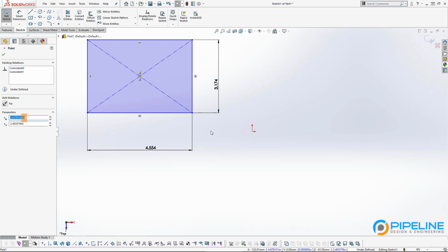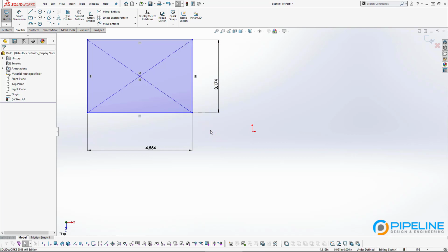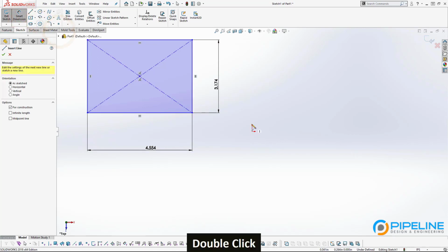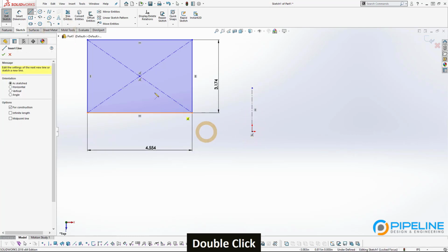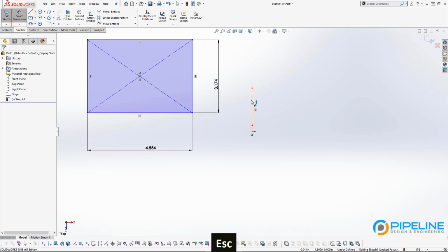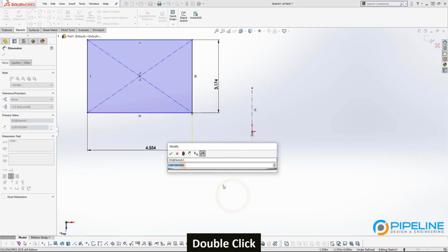you don't have a good reason to put it here. Generally, you want to think if you have a good reason to do something. In this case, there's no reason to put it out here, and you're only creating more work for yourself. You'll have to add more dimensions to make sure it doesn't go away. And that's a lot of work that you don't need to do because you don't have a reason to do it.